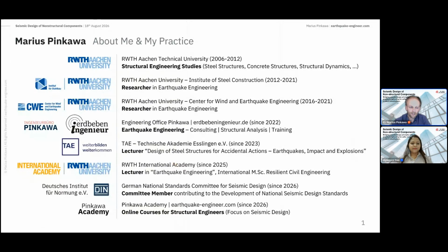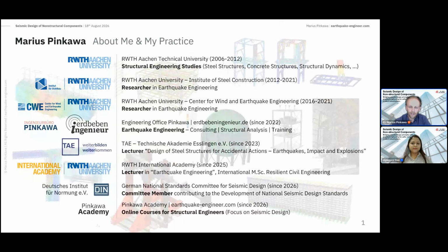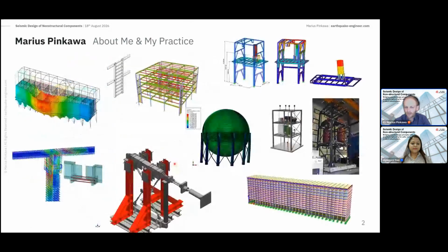So this is a glimpse at one of the larger projects I was working on at my time at the university. So we focused on optimization of structural systems like this one, because the current philosophy of seismic codes is that we have energy dissipation taking place, plastic mechanisms develop, and after the earthquake, the building is damaged, and usually it's a total economic damage.